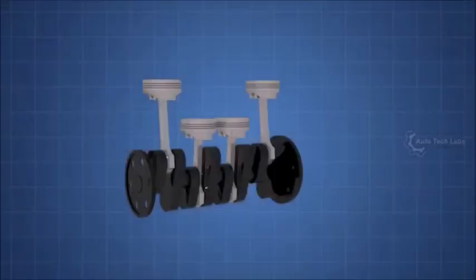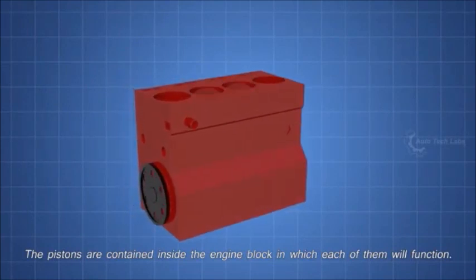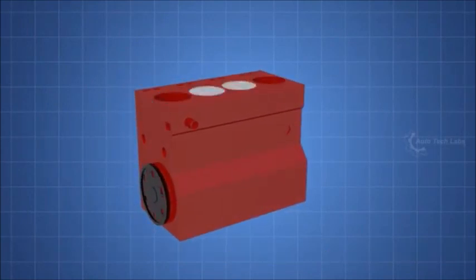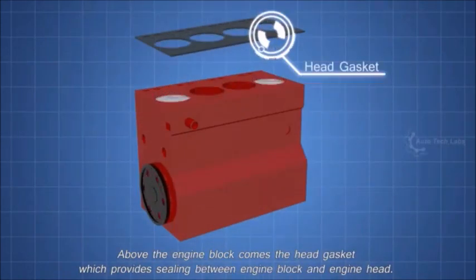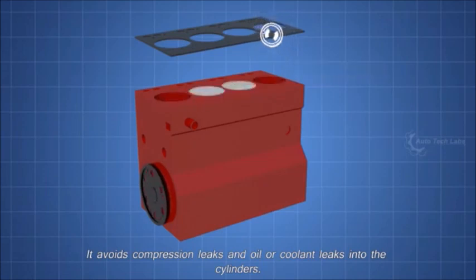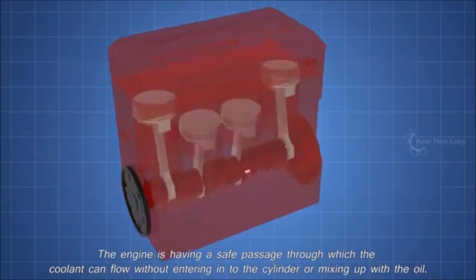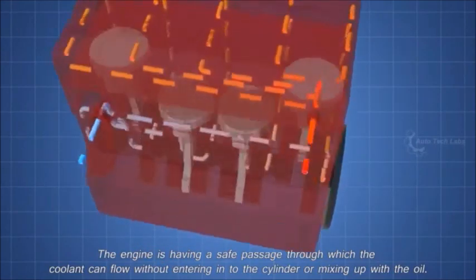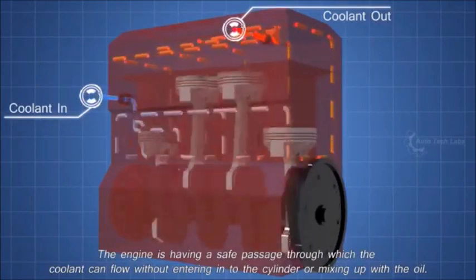The coolant temperature sensor consists of a sensing probe and an electrical connector. Most coolant temperature sensors are negative temperature coefficient type, which means that as the temperature increases, the resistance will decrease. The CTS can be a 2-pin type or a 3-pin type, depending on the make of the vehicle. These are the main parts involved in an engine cooling system.